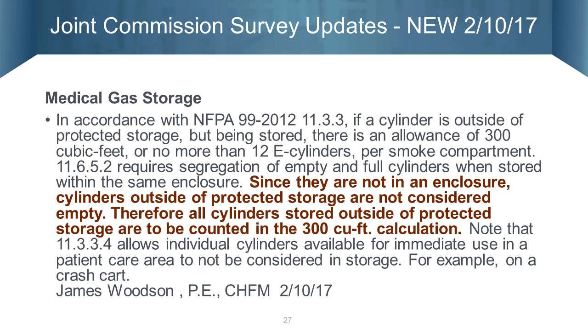And then medical gas storage. This is a new one that Joint Commission came out with. It's basically a clarification, I guess you would call it, but it's a significant change for us. It came out February the 10th. Basically it says that any oxygen E-cylinders in a smoke compartment that are not in a fire-rated enclosure must be considered full whether they're empty or not.